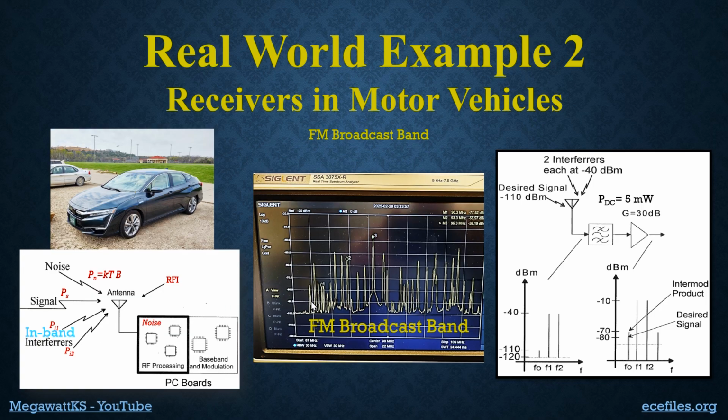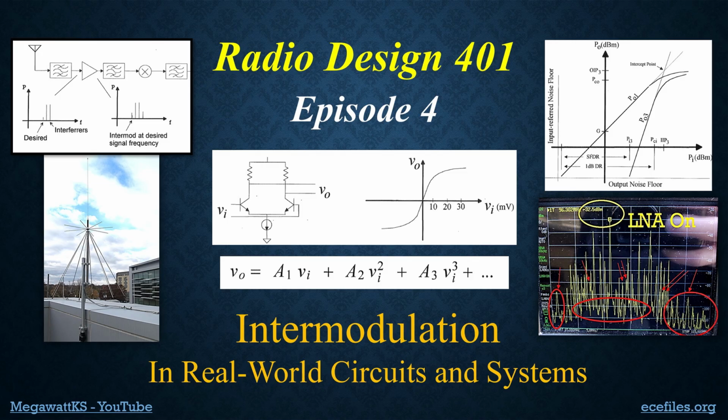But the signals then I'm calling in-band interferers. They're in-band because if we look at the block diagram over here on the right, there is a so-called pre-select filter that blocks things like Wi-Fi and frequencies that are well outside the FM broadcast band. But the entire band goes through this filter. And then it hits the low noise amplifier. And if there are some really strong signals, more than one, for example, they can mix together and create what are called intermods. And for details on that, see episode 4 in this Radio Design 401 series.